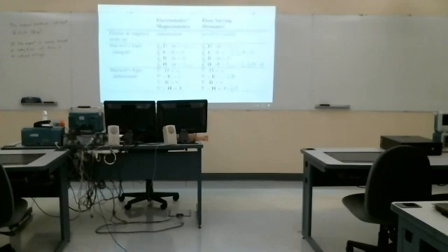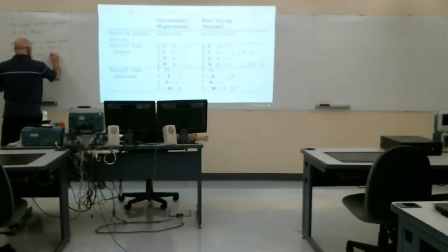Because I've got a resistor here, there will also be a current. So sometimes they'll say in this experiment you get an induced current. But there's only current if I've got a resistor across that connection allowing current to flow. So more properly, it's an induced voltage. I'll have a voltage there whether or not current is flowing in the coil. I'll have current only if there is a load across the gap, across the connection.